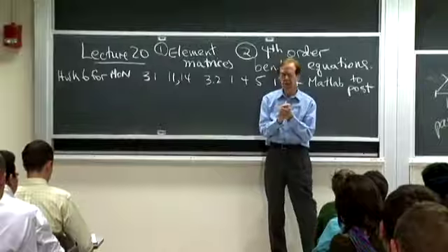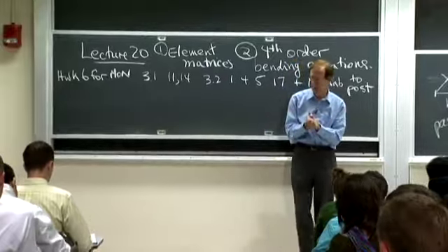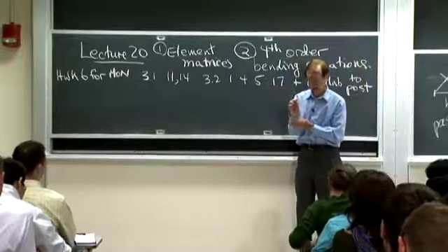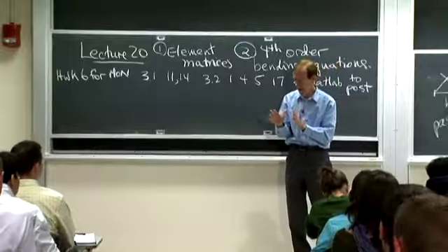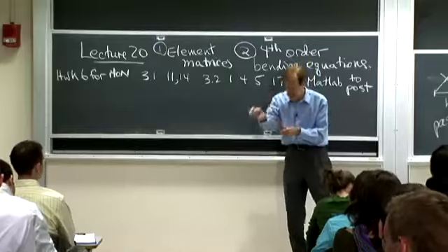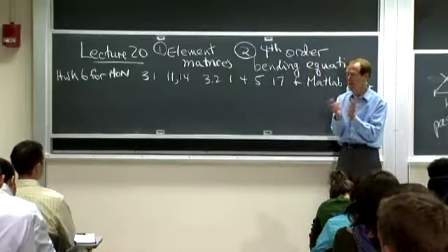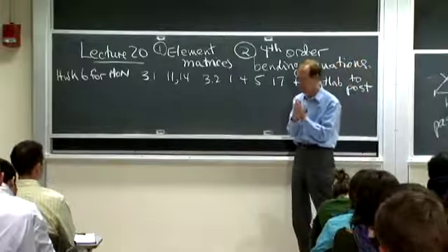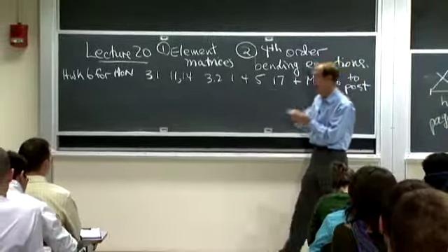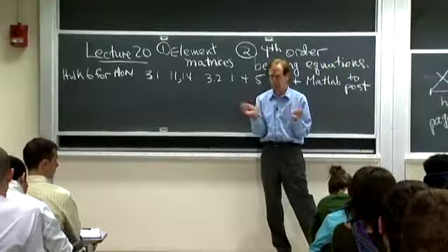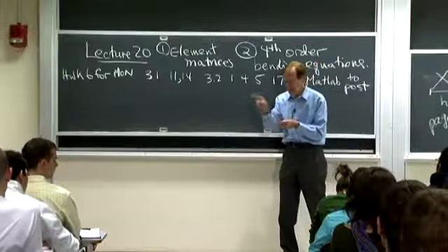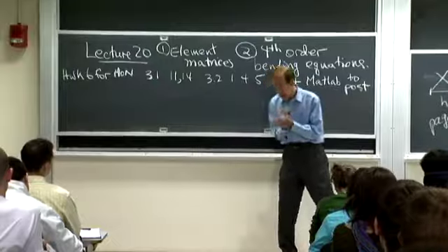One of those topics is the idea, still in the finite element world, of element matrices. You remember we saw that each bar in the truss could give a piece of A transpose A that could be stamped into, or assembled, to use the right word, K. For graphs, an edge gave us a little 1, -1, -1, 1 matrix that could be stamped in.